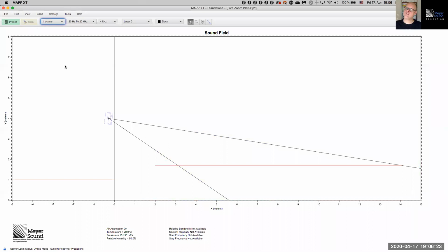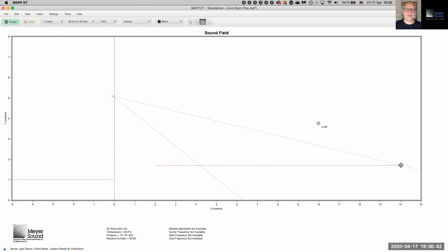Yes, that is the rotate tool. Let's select our center line and that vertical line, the line that represents the bottom edge of coverage, and let's pivot this configuration, but instead of doing it at the loudspeaker, let's do it at its destination. If we do it at its destination, I can now rotate that loudspeaker and its bottom edge of coverage, okay, and can put it up a little bit in the air.